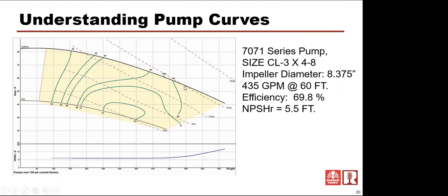First of all, engineers generally say, okay, if I want 700 gallons a minute at 40 PSI, I'm going to tell my pump supplier that I want 800 gallons a minute at 50 PSI, so I know I have enough. So I've already oversized this pump. When that pump comes into place, it doesn't know it was oversized. It doesn't know that it should only be producing 700 gallons a minute at 40 PSI. It's trying to produce 800 gallons a minute at 50 PSI. So we're already forcing this thing to move off of this curve just because the design was not exactly what we thought we wanted in that system.